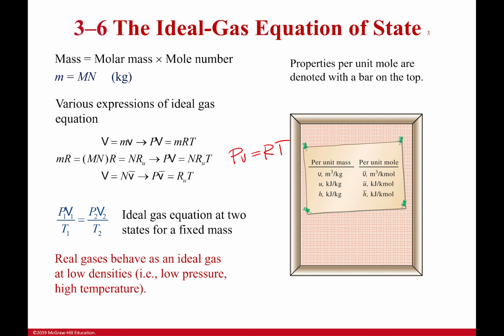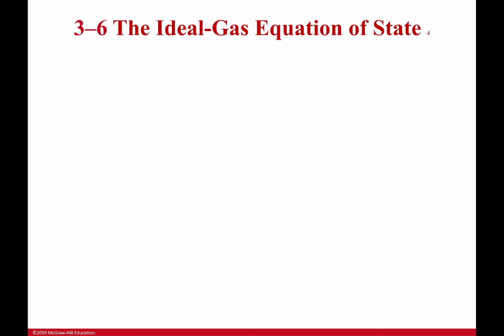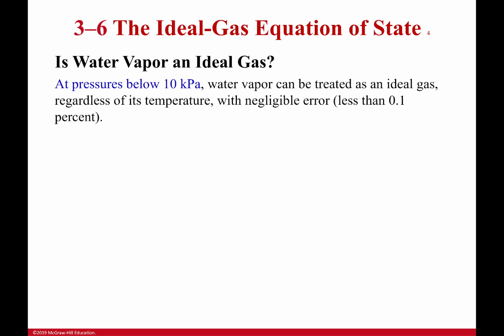Now, another question you might be asking yourself is, well, what is an ideal gas? Well, idealization is always a way of making things simpler on ourselves. Some gases act ideal in most cases. Noble gases, typically ideal situations. However, for real gases you actually encounter, like water vapor or air, they're only ideal at low pressures and high temperatures, or low densities. Air, typically an ideal gas. Water, not so much. And why is that?